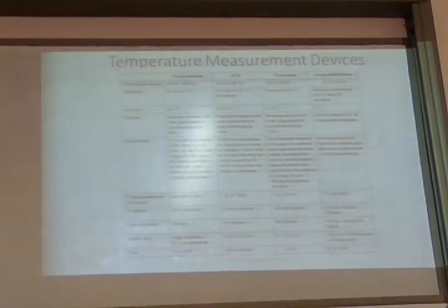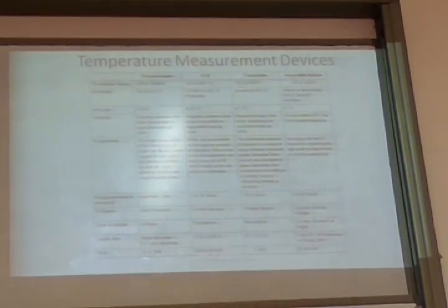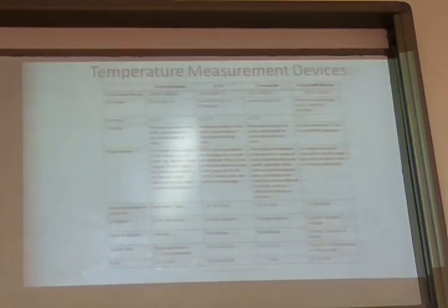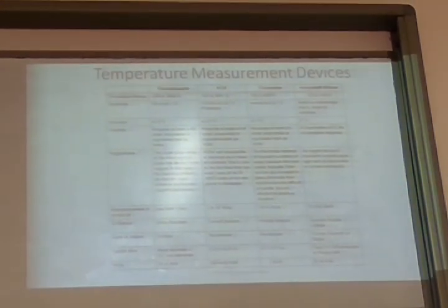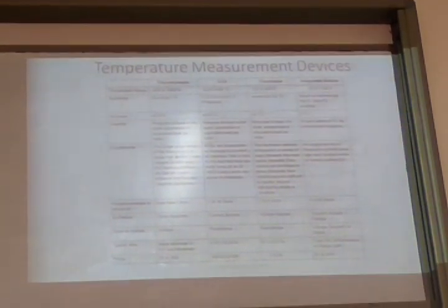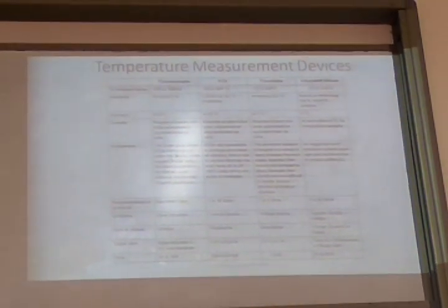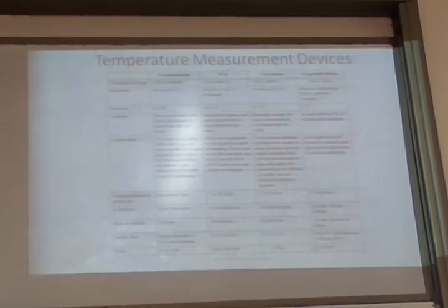So it generates voltage by itself. It's an active sensor. That's what you were planning to say, but I wanted you to explicitly spell it out. You have a temperature difference, and proportional to the temperature difference, the voltage is developed inside the circuit automatically. The sensor produces voltage, so you don't need to supply the voltage there.